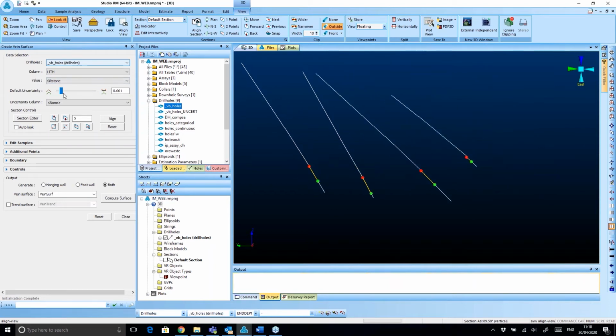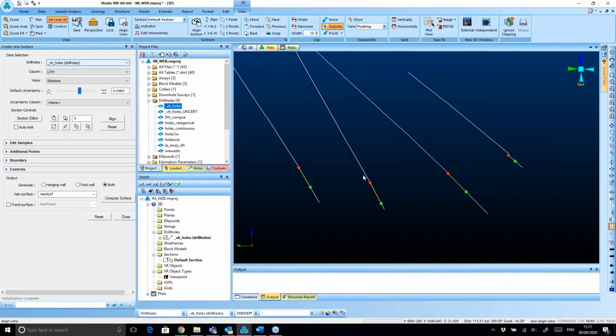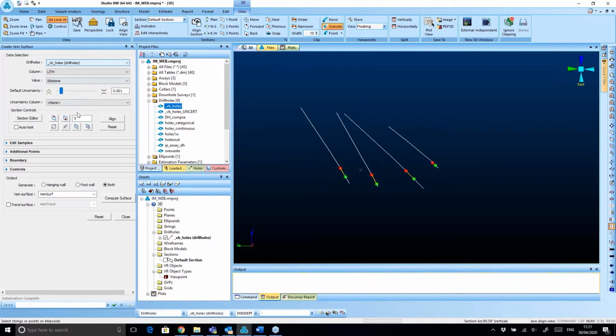Okay. But we also have the option to increase it. When you increase the uncertainty, that means you allow the system to generate a smoother wireframe. Based on the geometry of the wireframe, the system tries to create the wireframe as smooth as possible. And that's why in some places you can find that the snapping would be ignored, right? That's why we usually have quite a low value of uncertainty. Okay, something like this.